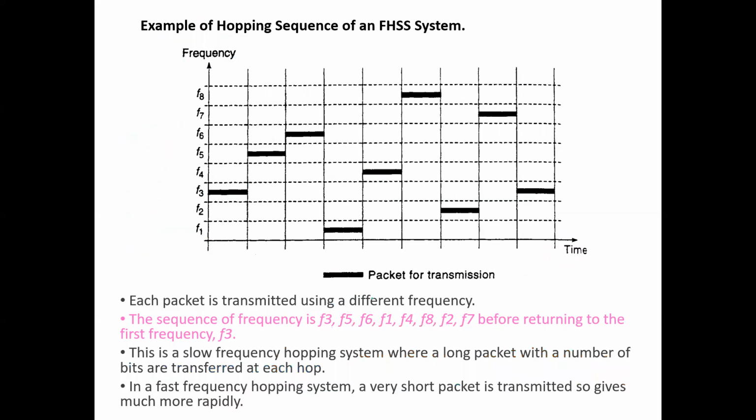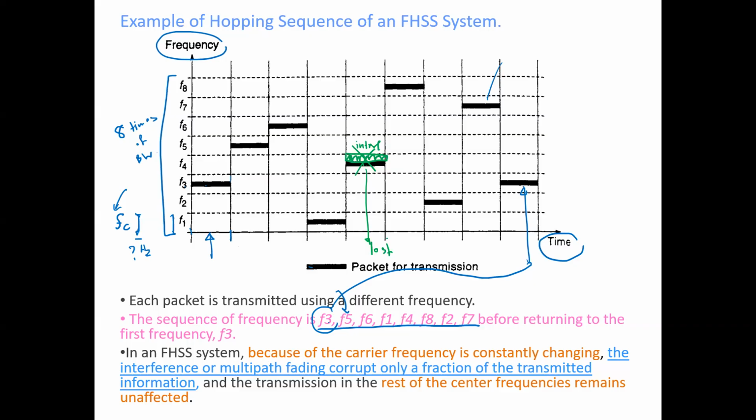Why not? We can do the retransmission, and the good thing about using frequency hopping is that by using retransmission, we do not need to send with the same frequency where we faced the interference. For example, here F4 has the interference, right? But frequency hopping has another frequency than F4, in the sequence of other frequencies. This packet that is already lost can be resent with another frequency.